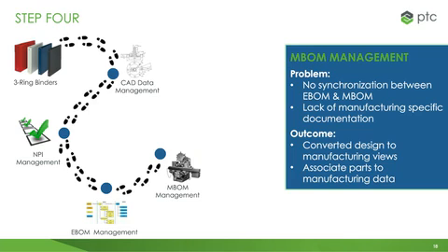Next thing we did is we wanted to be able to manage the EBOM and the MBOM individually. Because we were converting the EBOM into an MBOM, the EBOM no longer existed in PDM Link. We decided the best course of action would be to add an additional view to PDM Link. So this project consisted of converting everything in design view back to EBOMs, creating an additional view, which we called the manufacturing view, and we created MBOMs for every product that we made.